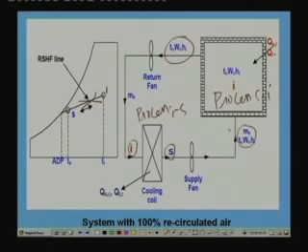As the air flows through the conditioned space, it picks up sensible heat and it also picks up latent heat. That means its temperature increases and its moisture content increases. And the same air as it flows through the cooling coil, its temperature reduces and its humidity ratio also reduces, because we have to go for a cooling and dehumidification process in the cooling coil. So as far as the conditioned space is concerned, it is heating and humidification, and as far as the cooling coil is concerned, it is a cooling and dehumidification process. If you plot these two processes on the psychrometric chart, they exactly coincide. Only thing is that the direction will be opposite.